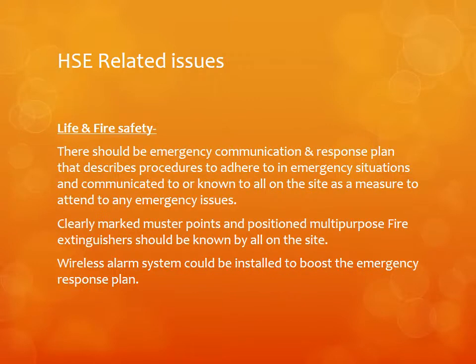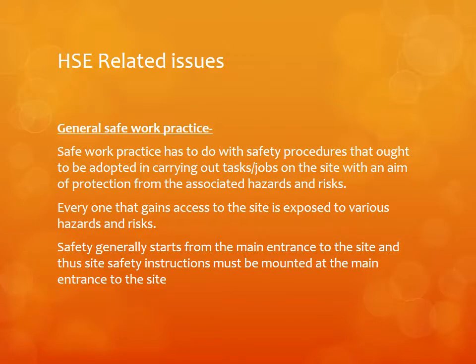For life and fire safety, there should be an emergency communication and response plan that describes procedures to adhere to in emergency situations, and it should be communicated to or known by all on the site as a measure to attend to any emergency issues. Clearly marked muster points, well-positioned multipurpose fire extinguishers, and a wireless alarm system could be installed to boost the emergency response plan. It's all about ensuring the safety of all on the works.